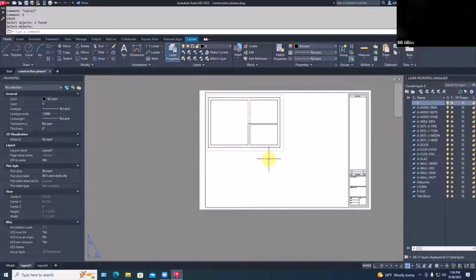The initial way AutoCAD came with, back when I learned it, was just what we've been doing here. If you wanted your text in a drawing to come out the same thickness as the wall, you made it 6 inches high. And if you changed the scale of that drawing, all of a sudden it was a different size on the plotted page. So to do that, you need a dimension style for each scale you were going to be drawing at. Say 1 for 1/4 inch, 1 for 3/4 inch, and 1 for 1.5 inches or something or other.